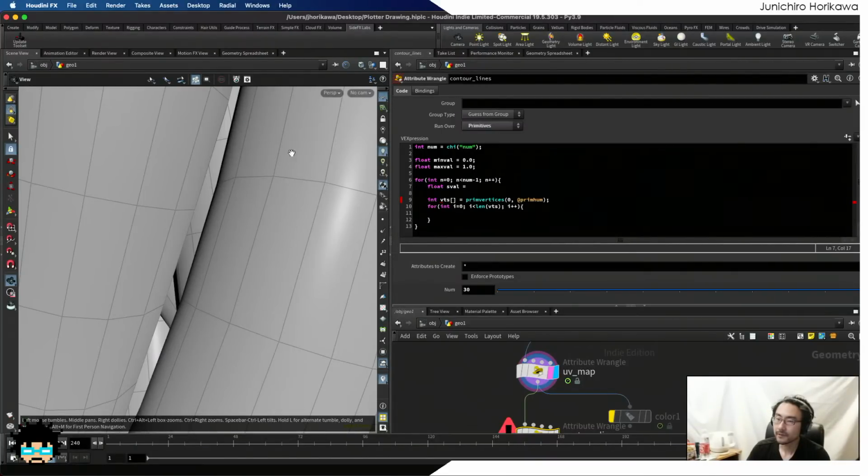In this case I want to go in this direction, so I want to cut in this direction. I want to use this edge and this edge to add the ISO lines. And in order to define in which position of the edge I would like to use it as a cutting line or cutting point position, I need to calculate that right here, and based on this number value.